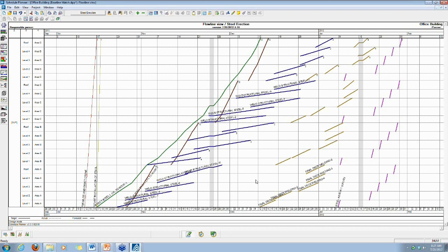It may also be a result of what we call disparate location breakdown structures, which means sometimes in your CPM schedule you will, without thinking too much about it from a relationship perspective, from activity to activity, implement some constraints, let's say material constraints or logistical constraints, by implementing some different location sequences.